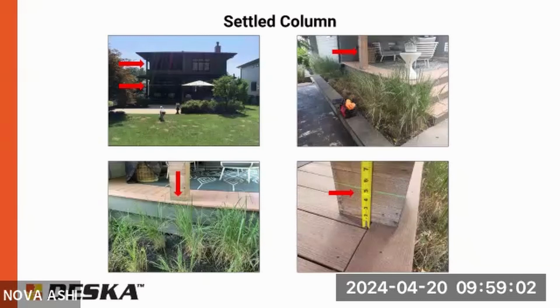But it happened. In this particular case, your options are either you move the column to an area that's suitable to support it, or you dig down, in this case, about 9 feet to the bottom of the basement footing next to it, to get to that same elevation, which would be a lot of work, especially with a deck already on top of it.